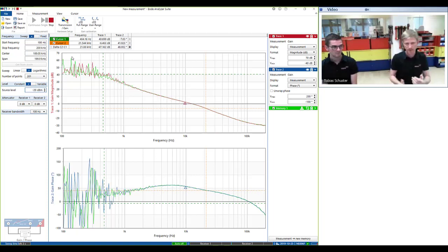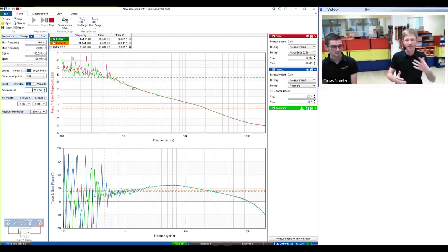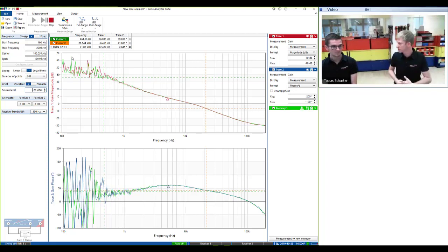The lower we set the injection level size, the more problems we have in the high gain area, where actually the control loop pushes the entire injected signal to one side of the injection resistor and the other voltage is very, very small.